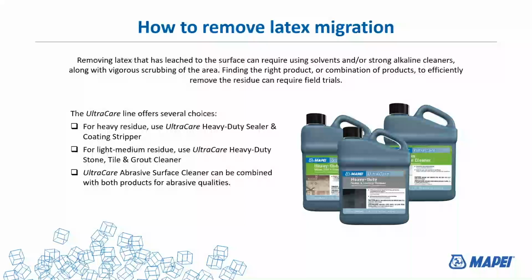For the lighter to medium residues, I would say our Heavy Duty Stone Tile and Grout Cleaner, an alkaline cleaner, would work quite well. The alkalinity, and there is a glycol ether type of solvent in it that helps dissolve latexes as well. It attacks acrylic and latex, so that helps, and it will remove light films of latex haze quite easily.